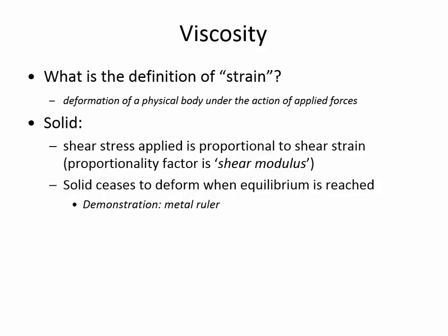What would you expect if this was made out of titanium? How would things be different? It would be harder for me. It wouldn't be as flexible because it would have a different shear modulus. The amount of force that I apply would cause less of a deflection.